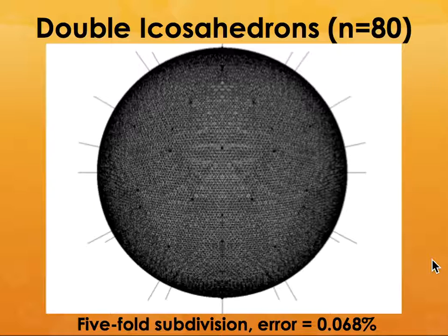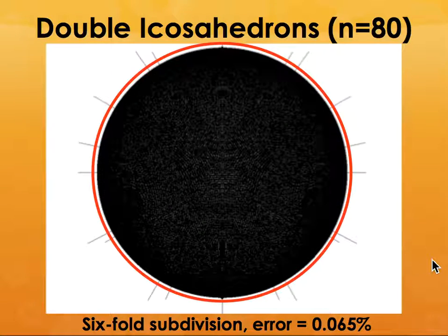What it shows is that by multiplying the number of triangles that you are using to represent a surface, you can reduce the error percentage compared to the actual part that you have designed.